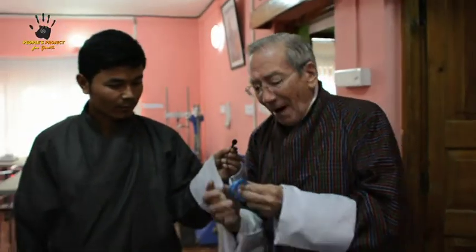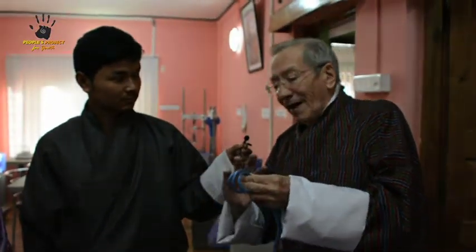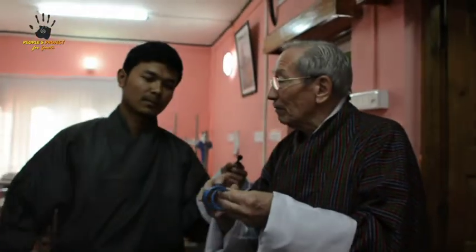So this is what happens. When I put a bar of iron near this coil, it becomes more difficult for the alternating current to go backwards and forwards. In effect, the resistance to the current flow becomes bigger. But because it's alternating current, it's not called resistance, it's called reactance. And so it becomes more difficult.